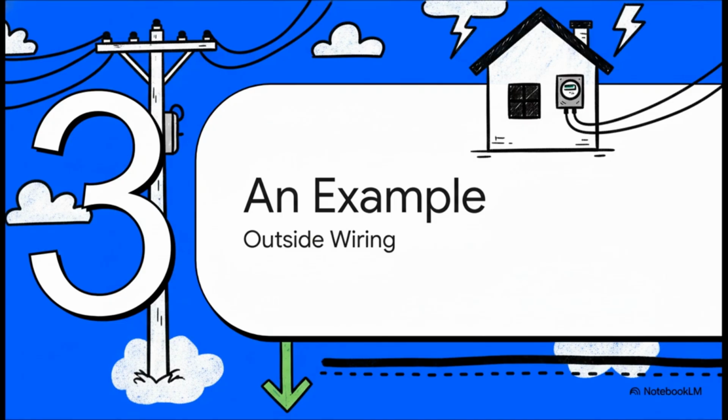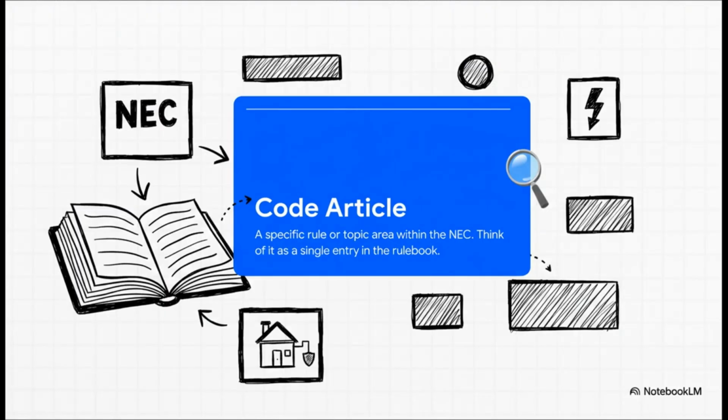For example, conductors for general wiring, Article 310, is referenced constantly. Okay, and Article 310 is what dictates wire size, insulation type, ampacity. All of it. So no matter what, I have to follow the sizing rules in 310. Why is that specific reference so constant? Because the wire itself is the common denominator. If you use the wrong size wire, if it's too small for the current, it's going to overheat and fail. Doesn't matter where it is. Doesn't matter if you're in a dry office or an explosive atmosphere. Article 310 is about the physical limitation of the material.